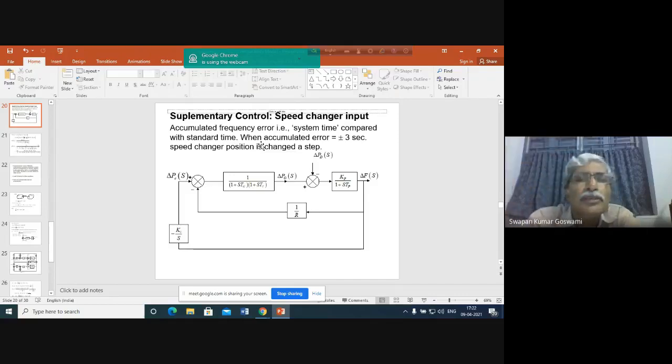The system was not in demand of power then, because during night time the load connected to the power company is reduced, and the load connected to the overall system is much less than the normal load. So when the system load is less and the system frequency is on the upper side, this generation company injects power into the system. Since power supply is then more than the demand, frequency will increase.